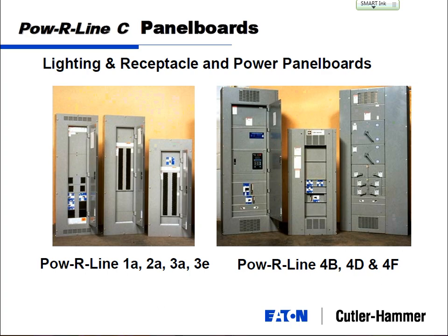Power panel boards, I generally consider them power distribution panel boards. So these may be at your point of load, maybe one in a room like this. This may be one per floor. So you're feeding from your main switchboard up to a power distribution panel, which has 5 breakers in it that feed 5 lighting and receptacle panels. And that's a typical application for that.